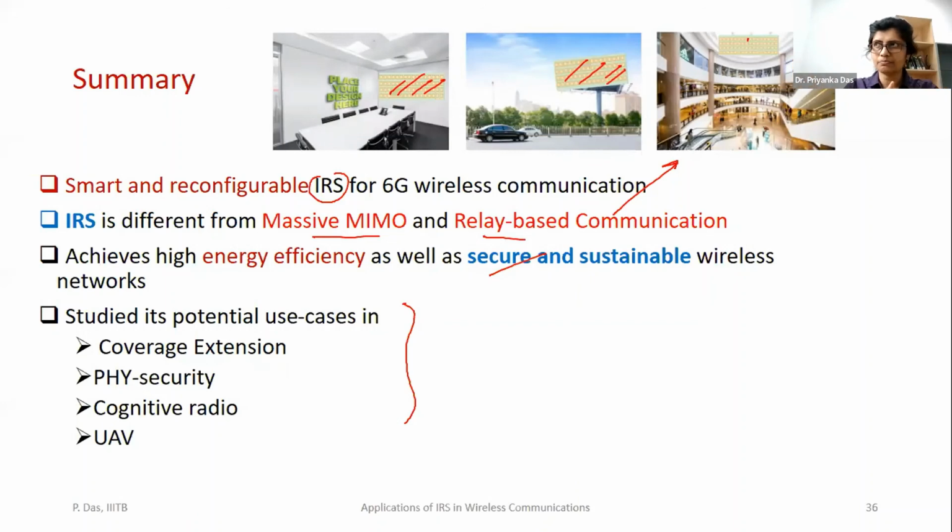In a cognitive radio scenario, if you have two IRSs, you look for the best SNR at the destination, subject to meeting a constraint. The constraint might be protecting the primary receiver from full power. If I tolerate hampering the primary with 10 dB of interference power, you can do that and choose the IRS which will provide maximum benefit for the secondary.